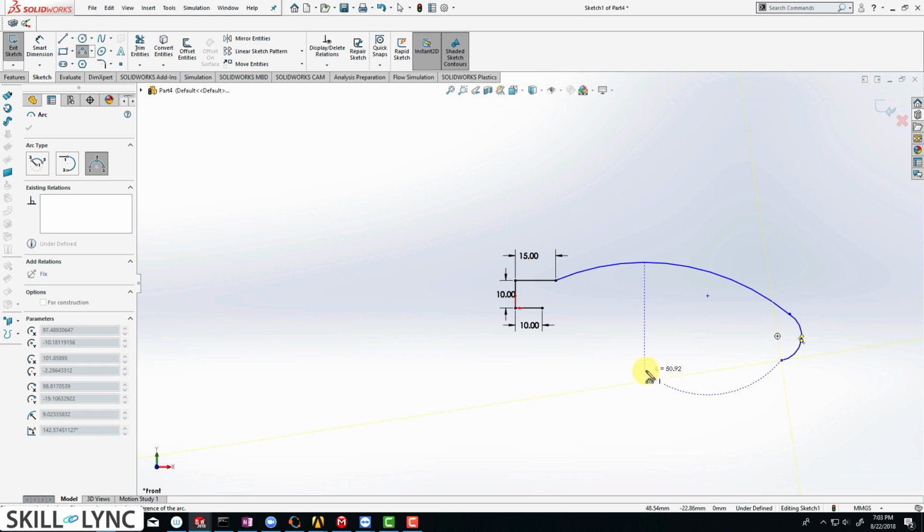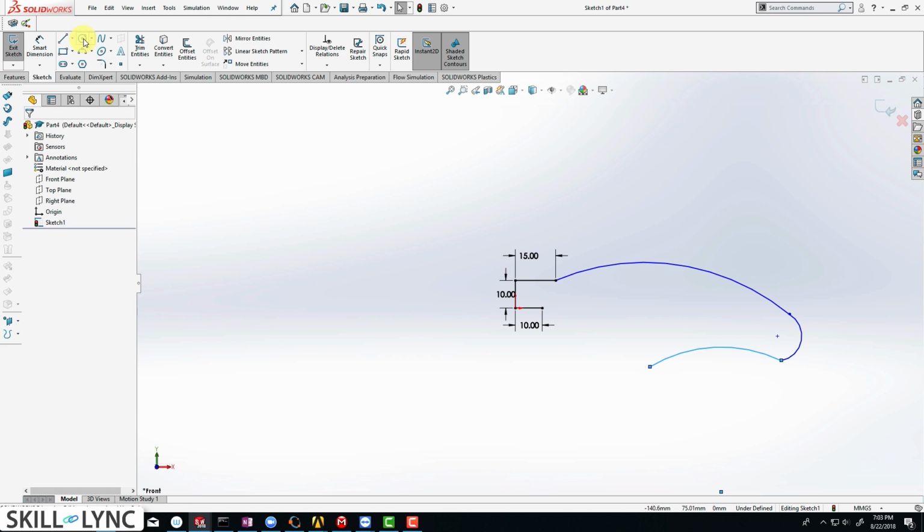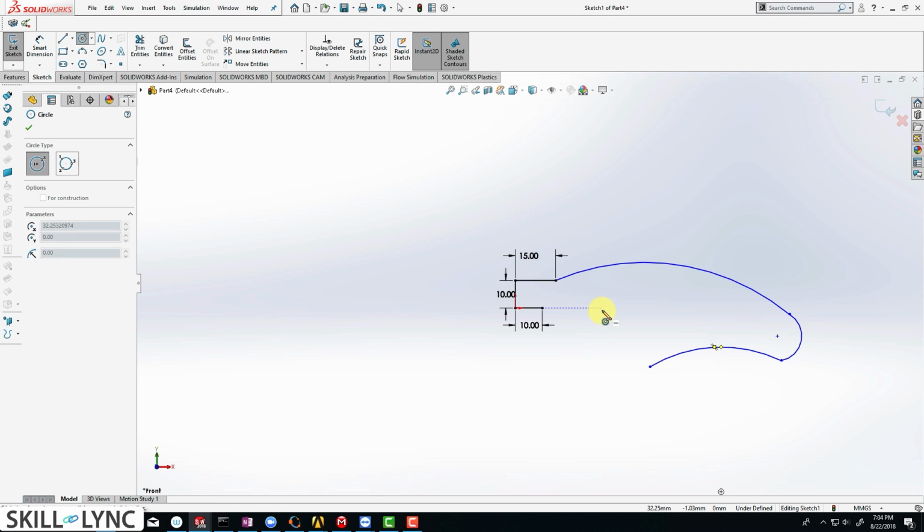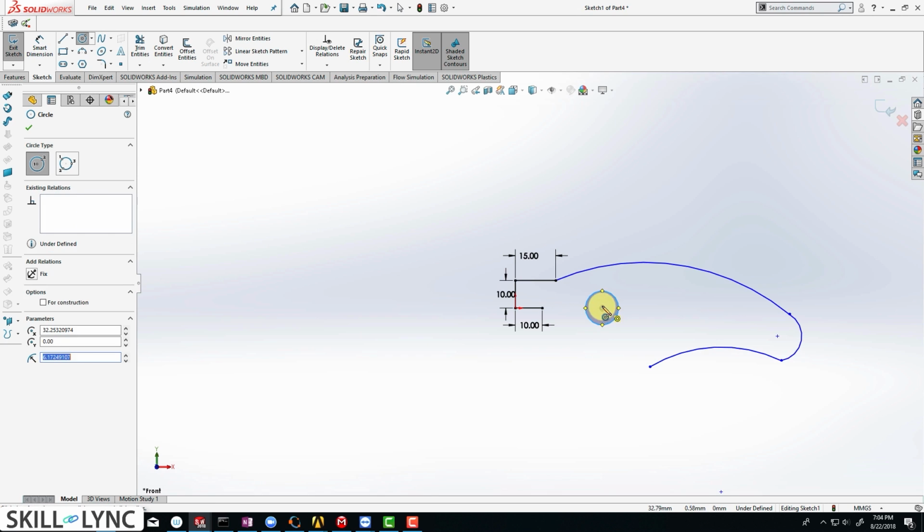Basically we are trying to draw the rocker arm. There are multiple ways to go about the same thing. Here I'm just following a particular method. Oh, actually, before we do that, we need to click on the circle tool to basically create the hole that's found in the center of the rocker arm. So let's click and drag it out and let's create 2 circles and hit escape.